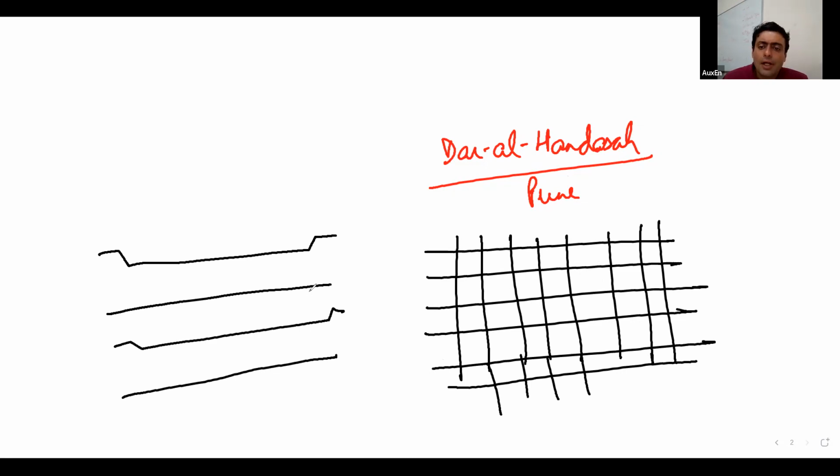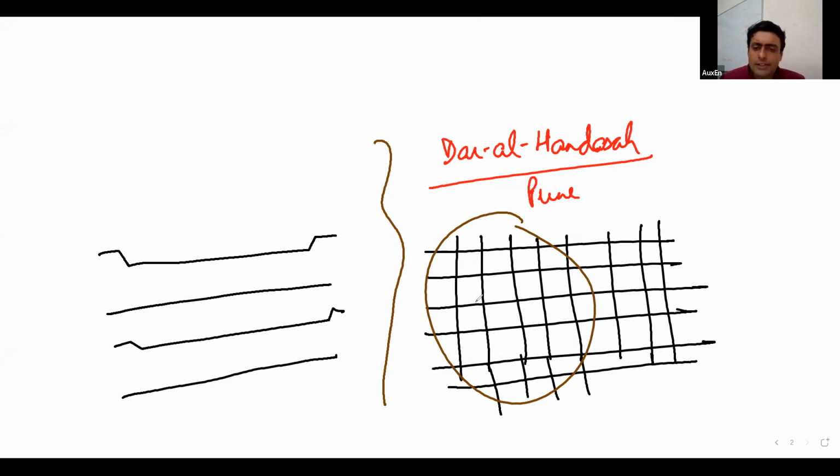All right. So there, when we used to do Middle Eastern projects, we were not very much concerned about the cost. We used to provide mesh-like reinforcement, top, bottom, no extra, nothing. Whatever is the maximum steel, just provide it in the form of mesh. Done. So there the equation is different. All right. There the labor is expensive. So they don't worry about extra cost that you put in reinforcement as long as it's easy to construct.